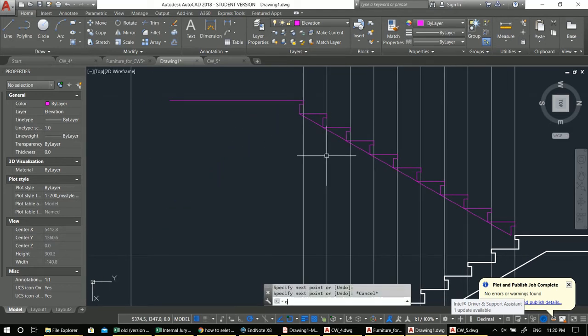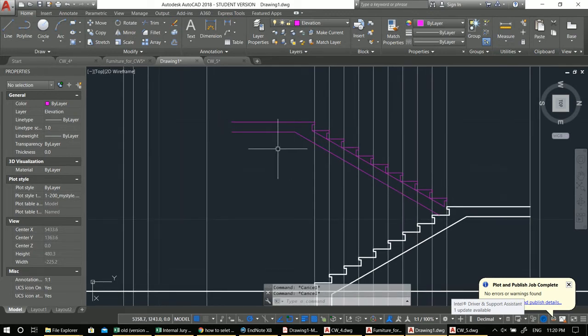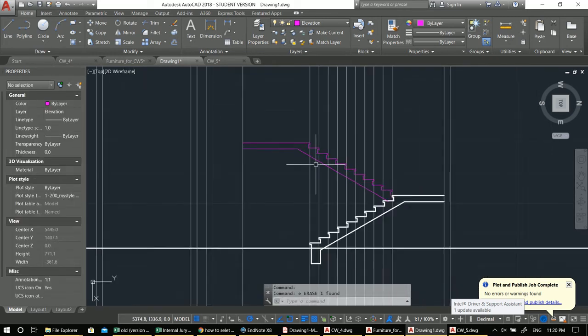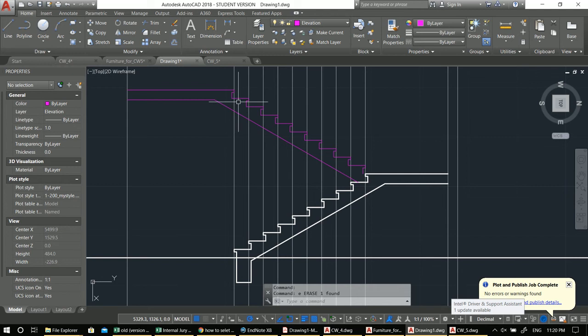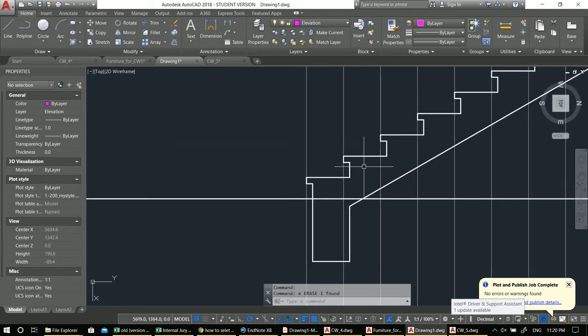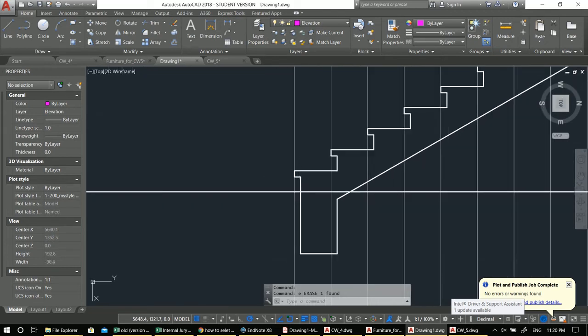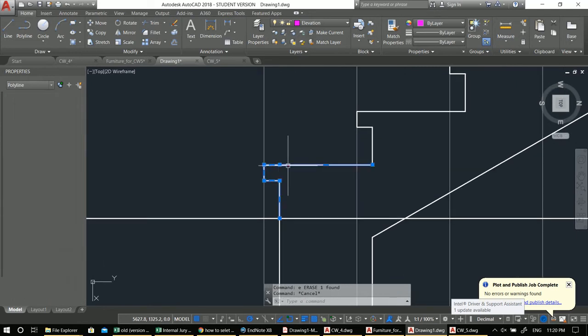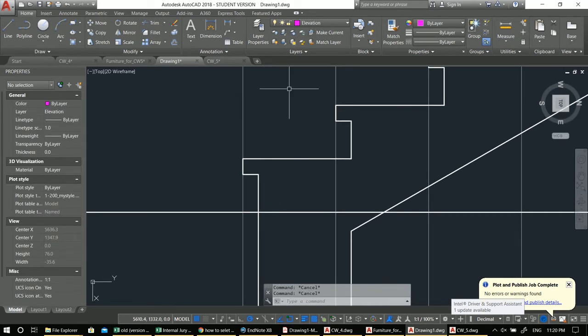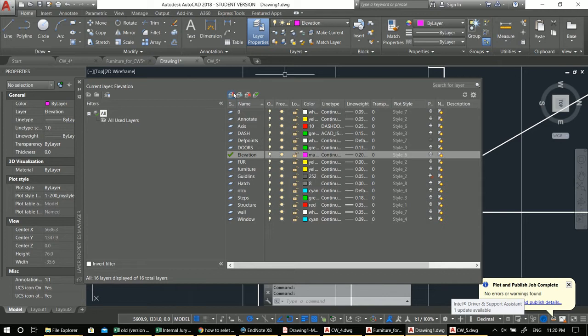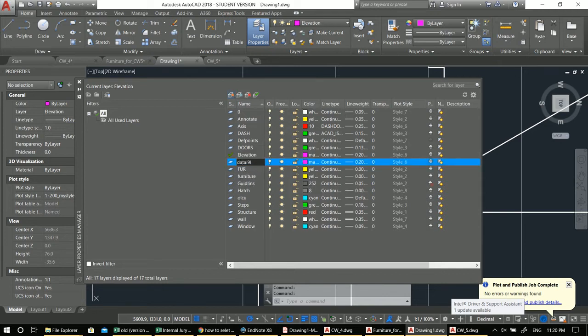So same procedure, offset 20, 20, fillet, extend, and this line doesn't actually exist in reality here. I mean, it exists, but it depends on the detail. We will add something here. If you're cutting and you're trying to draw a kind of system detail here, it's nice if you can draw more detailed structure. So if you add a layer called, like, I don't know, detail or something,